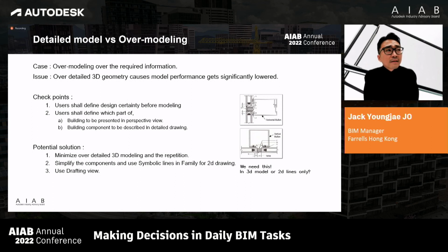And also I have seen a lot of projects where, by the requirement, we need to indicate the position and the size of tactiles at the access point of the staircase. I recommend my colleagues to present these parts as 2D lines rather than 3D geometry, because we may think that those parts are very small.